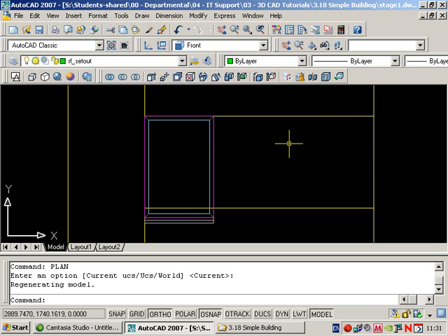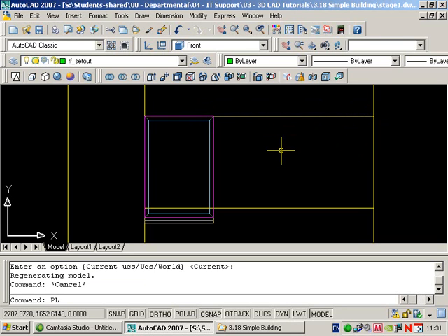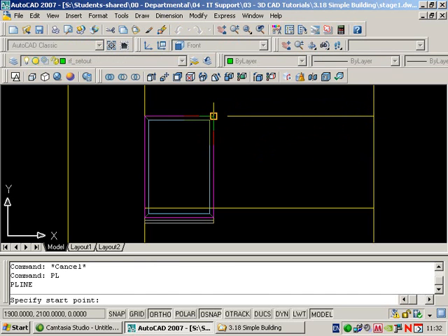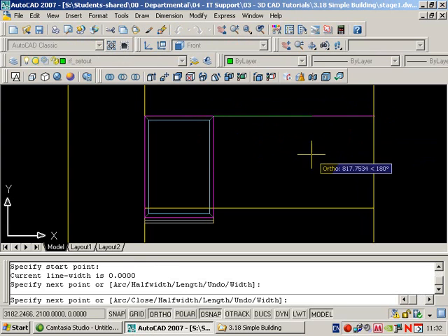I don't necessarily have to know a dimension there. I can draw a polyline over the top of that. Now, polylines do not vary their Z coordinates, so the line that I draw will be true. It will be straight from that position to there. No deviating backwards or forwards in 3D space. So PL, return, from endpoint to endpoint, return.